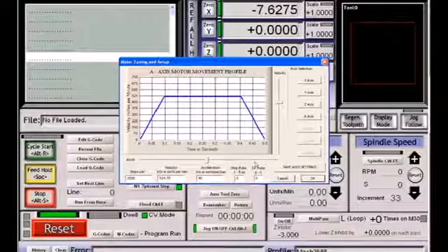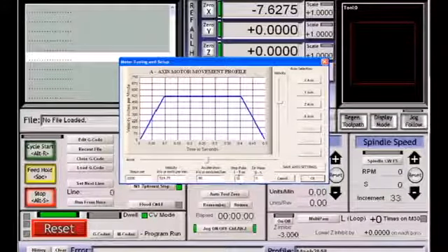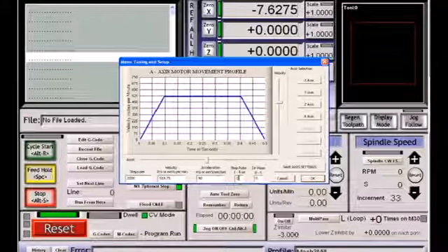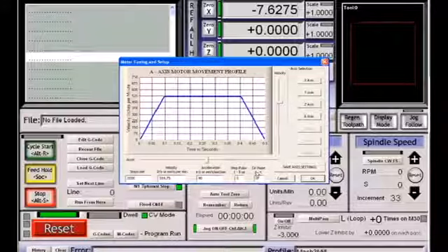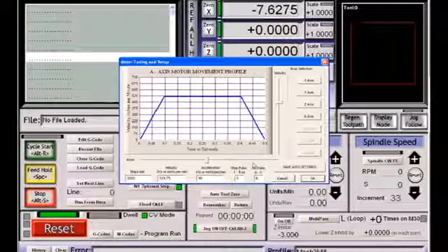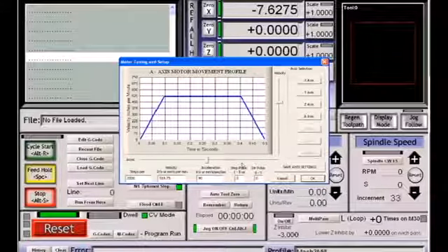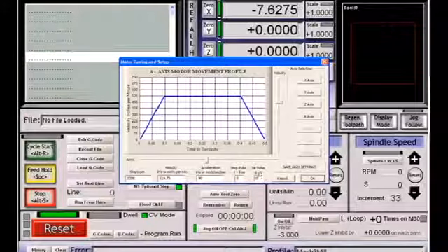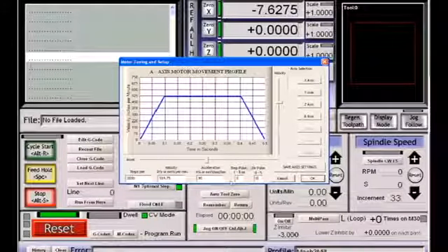If for whatever reason you find that your motors are not moving when you're using your up and down arrow keys, or they sound bad, you can use these numbers to increase between 0 and 5 the step pulse width or the direction pulse width. The only time you'll change a direction pulse width is if you find that you're losing 1 step each time you change direction. For 99% of users, you will never change this above 0. For 90% of users, you will never increase the step pulse above 0.